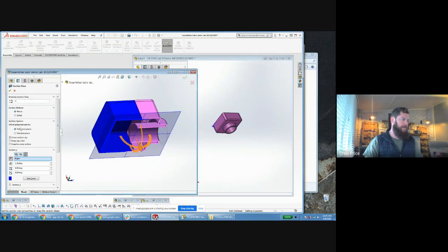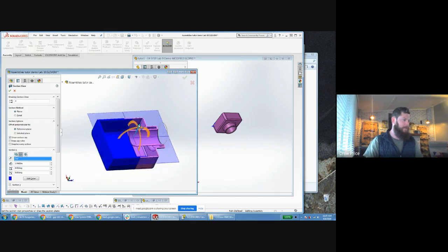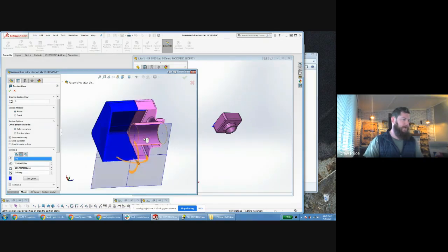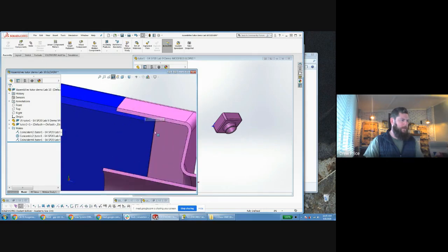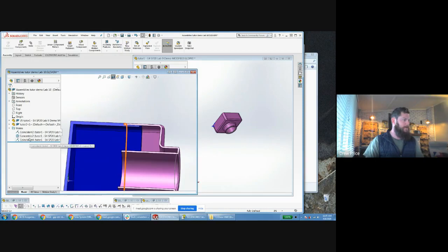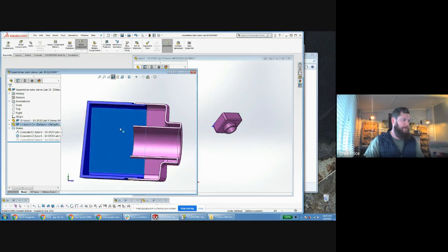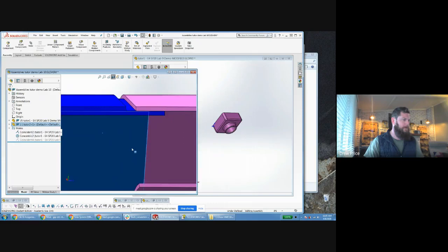And over on the menu section on the left, under section, you see it gives you the principal planes within the assembly that you can click through and drag your section plane to different orientations, so that now this section plane button at the top is selected, and I can zoom in and look at this mating interface of where my two parts actually slid together. So if I do the same thing and suppress this mate over on the left, even within the section view, now I can see in the section view where my parts come together.